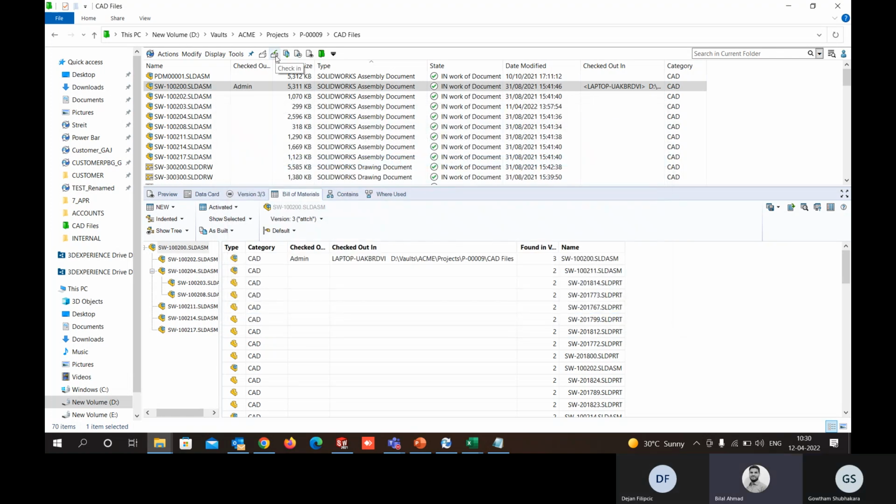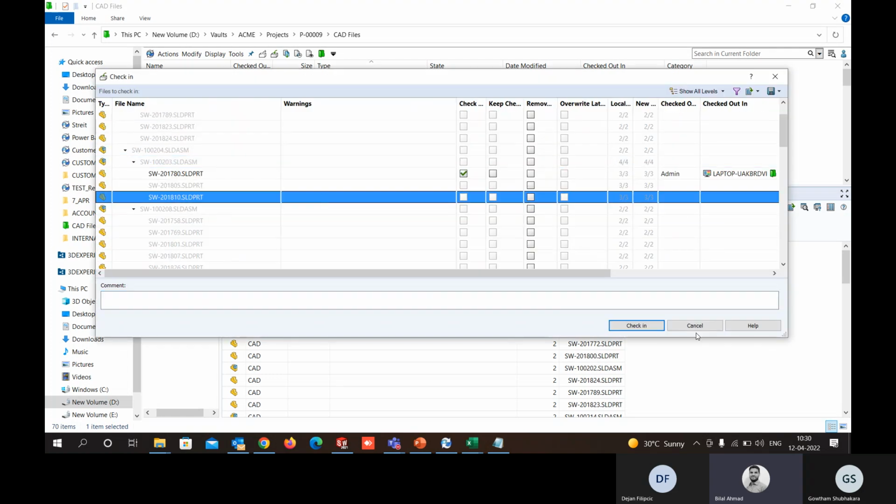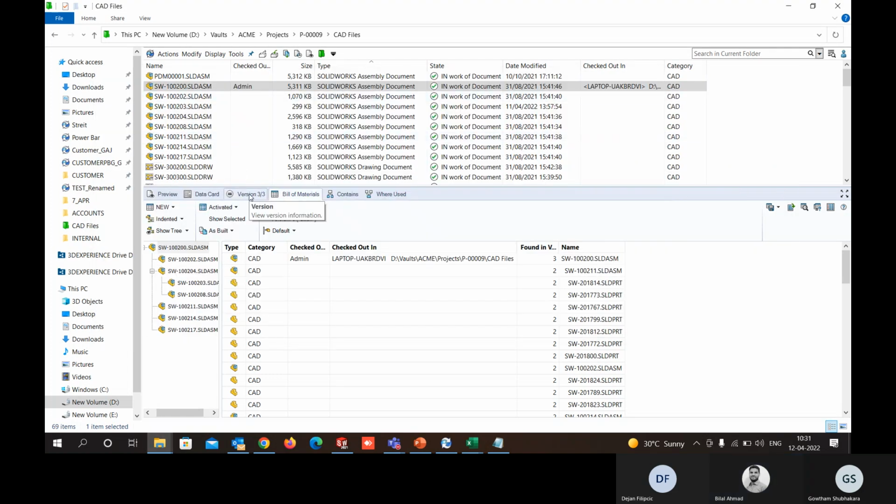One more point for this. When you create the bill of material and it shows, can you switch the tab? Well, one thing to do to solve weldments would be to simply go and redefine the entities based on our ERP names, because at the end the name of the entity is defined in the system in the library. So if we reformat that to match the ERP, when you make the BOM, the name will match.